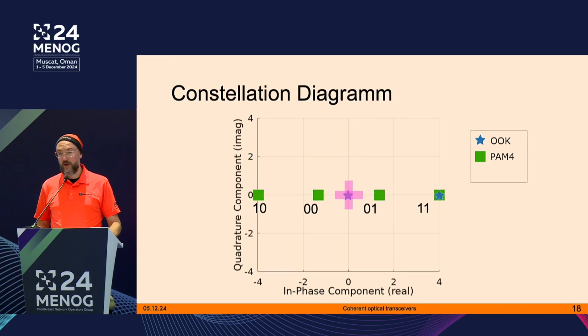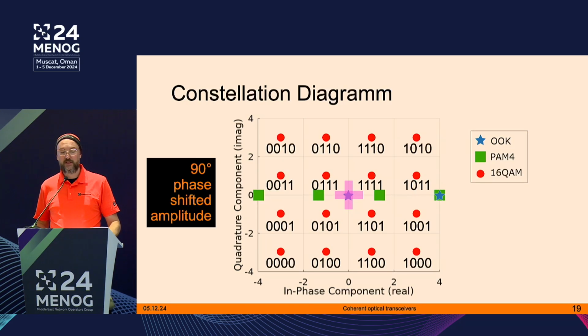We're looking at a 100 gigabit signal, which is typically modulated in PAM4, four-level pulse amplitude modulation. We have 4 dots. We have the great thing now, we can modulate 2 bits per symbol, so each square here is a symbol. Which is helpful, so we actually increase the bandwidth just with a new modulation scheme, but it's still in phase. And now, when we add the phase to our signal, it looks like this.